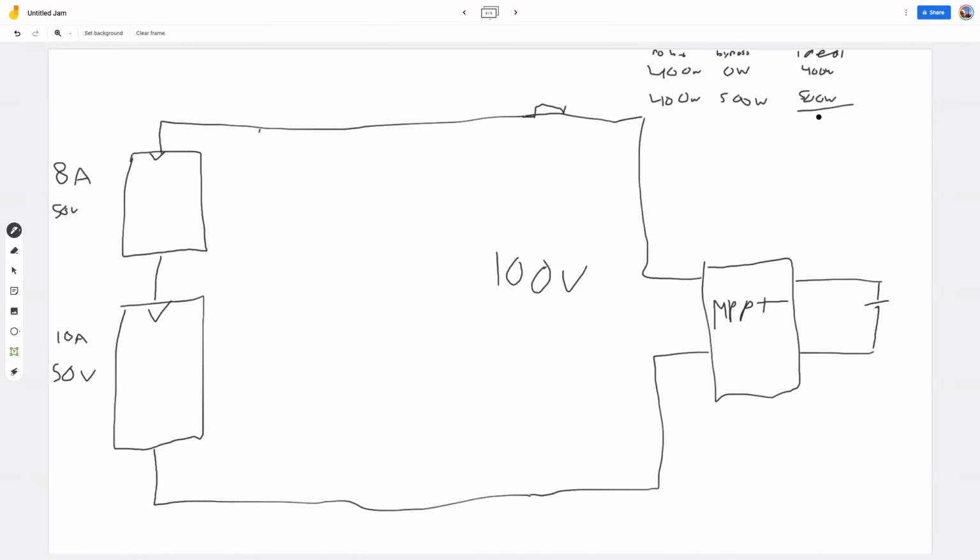So in the ideal scenario, you would like to get 900 watts out of your solar array. By using a bypass diode, which is not an optimum maximum power point in this scenario, you get about 500 watts out of your array. And by running the array at 8 amps, which is ideal for the top one but gets you less power out of the bottom cell, you get 800 watts out of the array. So the bypass diode scenario is possible, but not desired. The other maximum power point is also not desired because it's 800 watt and you would ideally get 900.